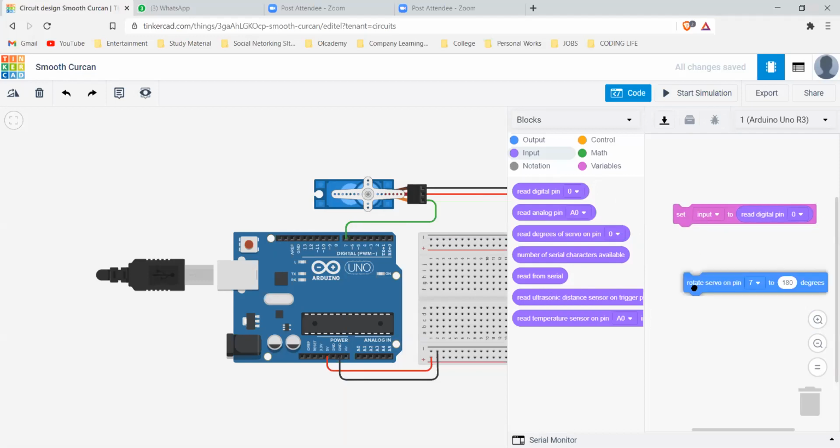Now you can actually observe that this pin will generate some kind of value, that is 1 or 0. Once it generates the value, the servo will actually rotate. By how much? By 180 degrees. Do you want it to just rotate at 180 degrees and stop? No. You want it to alternate between rotating left and rotating right. So you're trying to control how the system will work.